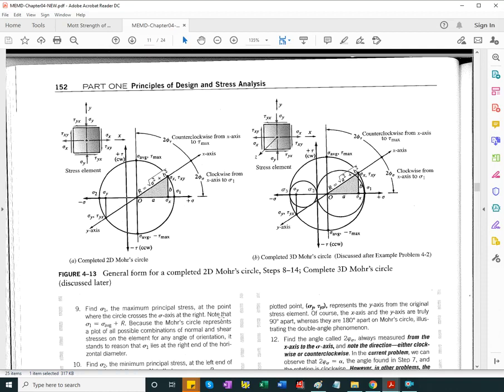In chapter 10 of the strength book, there's less emphasis on what is called the three-dimensional Mohr circle. We like to do a complete diagram by adding the third stress. Here I have sigma 1 and sigma 2, the principal stresses, assuming zero normal stress on the element.